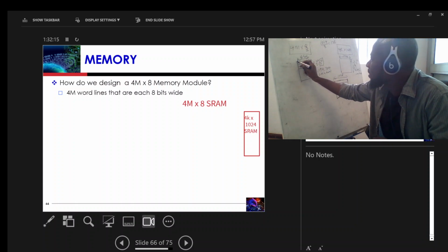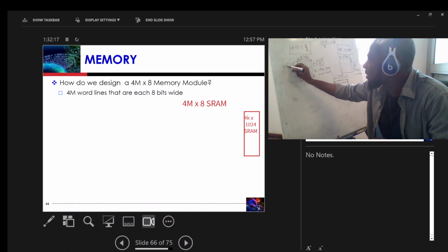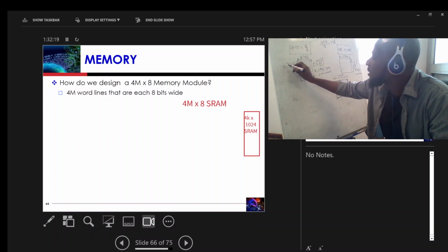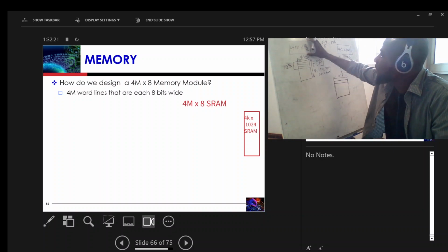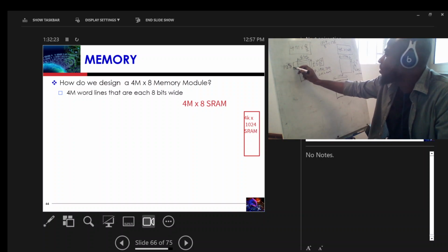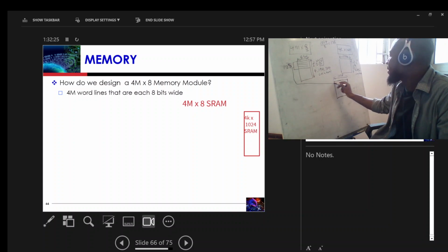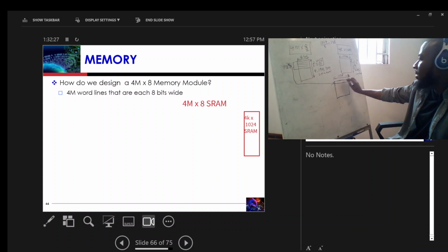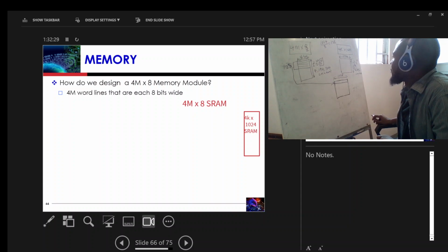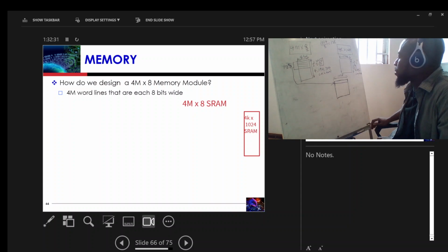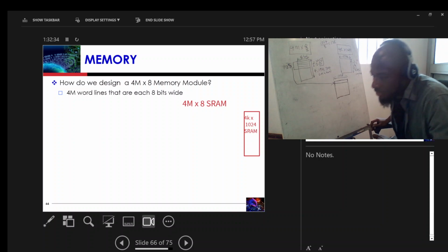So 128 locations within my 4M by 8 will be stored in just one location of my 4K by 1024 SRAM, right?